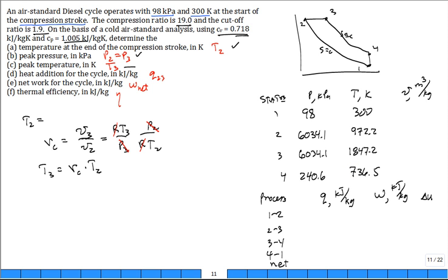Notice this pressure at 4, right before you're modeling the blowdown followed by the exhaust stroke, followed by the intake stroke. That pressure is greater than atmospheric pressure, and so that's why you have a large rush out when that valve cracks. In the analysis, we just begin a constant volume cooling.